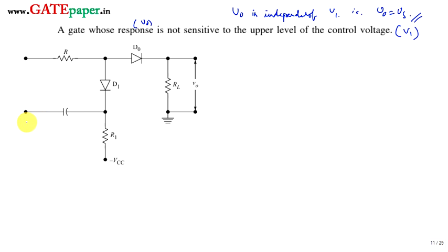How are you going to get this? This is control signal Vc and it is Vs. Let us assume we are discussing only the transmission period, so that Vc is at V1. Otherwise it may be at both levels, V1 and V2. We will discuss one by one. So case 1, when Vc is at V2, V2 means a large negative value, remember that.